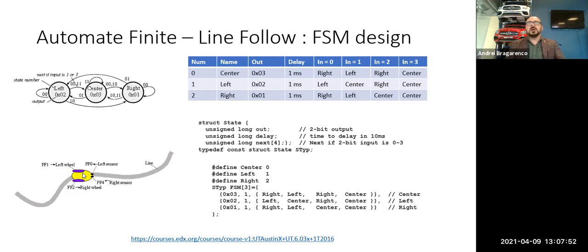So when we are in a situation when we have to define the behavior, the best approach is to use finite state machine, meaning that we have different states, and in different states we have specific actions, and we have to change between states by following some inputs. This is the general idea of the finite state machine. Everything else is just practice, practice, and practice.